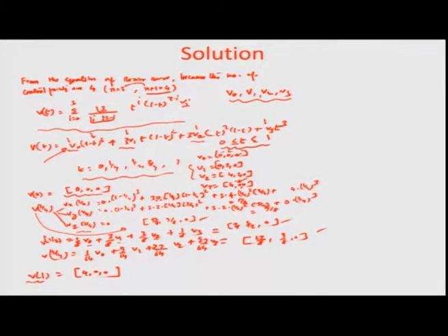These again, for the illustration of all readers, are basically the points which are control points. The curves will not pass through them necessarily, they will only pass through the endpoints, but in order to define the Bezier function, etc., they are absolutely necessary. But when the Bezier values actually prop up, they correspond to the values taken by different values of t, that is 1/4, half and 3/4, and when we solve these problems, we get a set of coordinates here, all in 3 x, y and z directions, corresponding to the different incremental t, which is there in the parametric form of the equation.